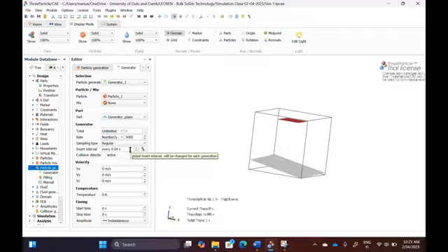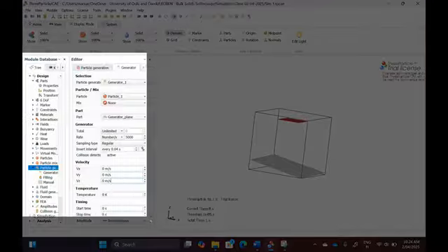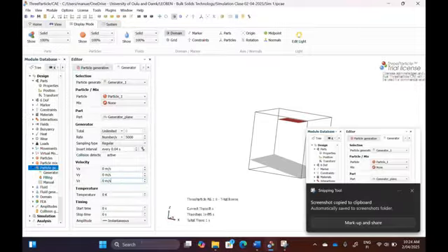And we also want to have a good recommendation, probably also to write down an initial velocity, because when we create the particle, it has 0 velocity. So you create it and it starts falling down. So if you have something like an opening where particles are falling out, you should already have a little bit of velocity, like minus 2 meters per second. Why minus? Because it goes down in the direction of negative. Minus z means in that direction.